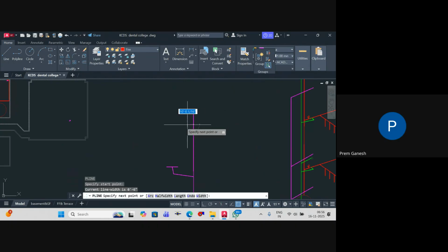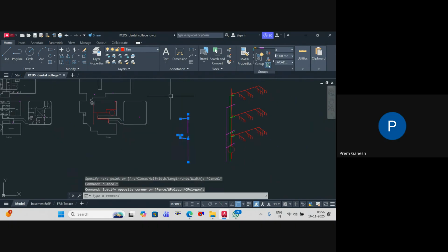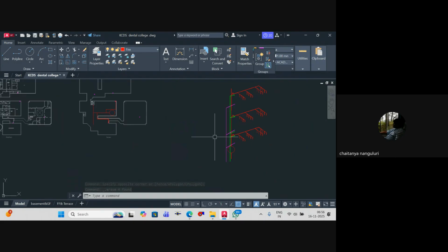But most of the times that hydrant drain will be separate only, right? Need not be. You can connect the sprinkler drain and this drain also together. There's nothing wrong if you connect it. I mean, if you can connect, you can connect. There's nothing wrong with that. That's what I meant to say. After the drain point. Done, done. Yes, sir.